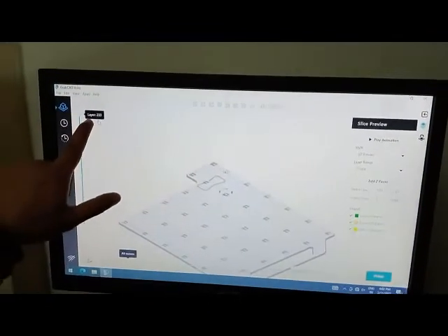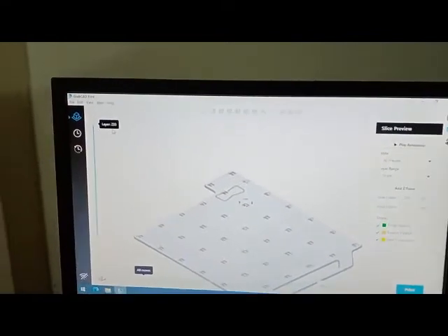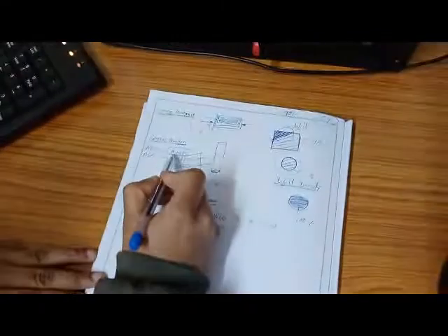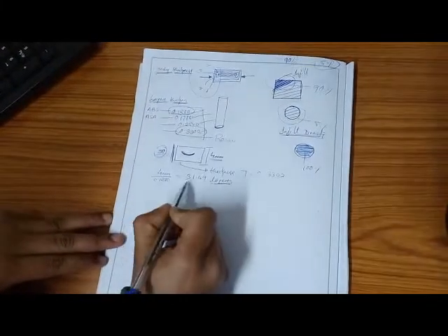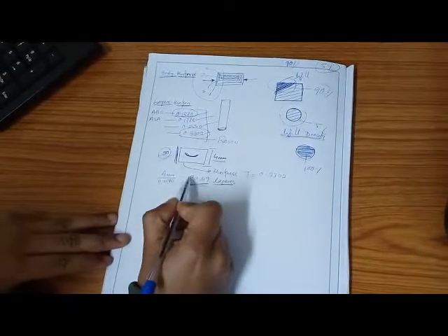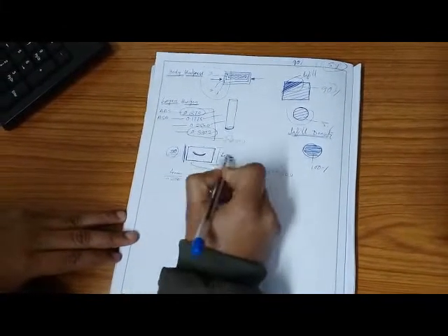In the slicing position we can obviously find the total number of layers, how many layers it will form, by using the slice. Also mathematically we can find it; it depends on the resolution. So the importance of resolution is to find the number of layers also. This many, 31 layers, we will have in this part. Fine, it depends on the thickness in z direction.